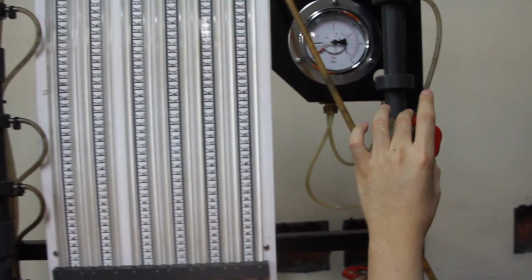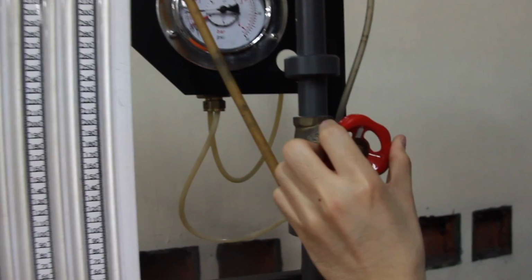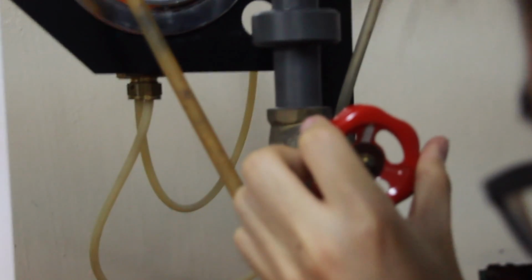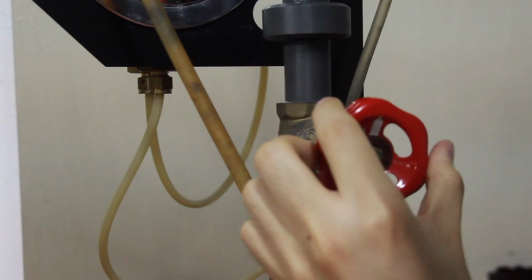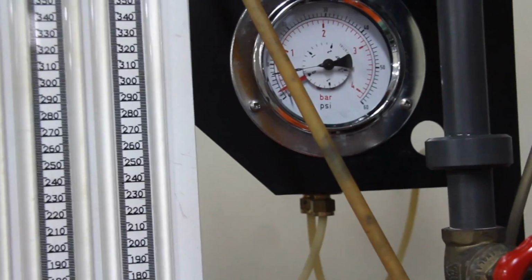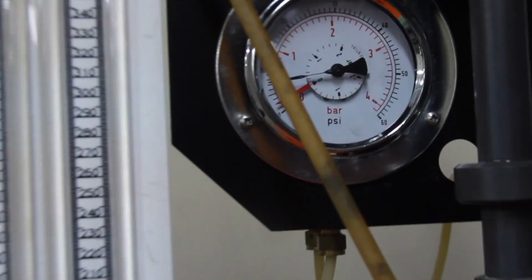The second trial is opening the gate valve at approximately 100% of one turn. Again, measure the pressure drop across the valve using the pressure gauge. Adjust the flow rate by use of the test rig flow control valve if needed. Determine the second volume flow rate by timed collection.